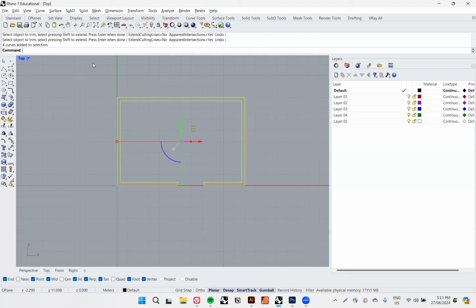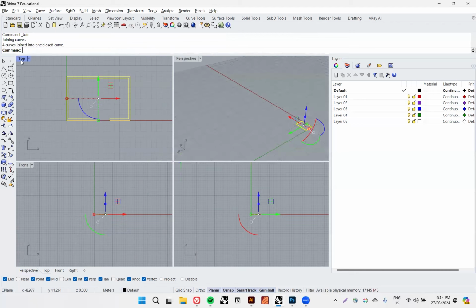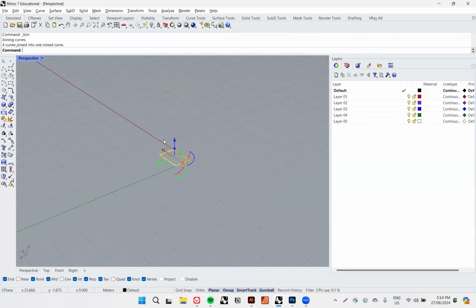No. In Rhino, I want to see you guys building your models correctly because it's going to bite you later. You are going to regret it, seriously. So that means stick to solids, don't really use surfaces unless you need to, because surfaces and solids act differently when you want to subtract from them.